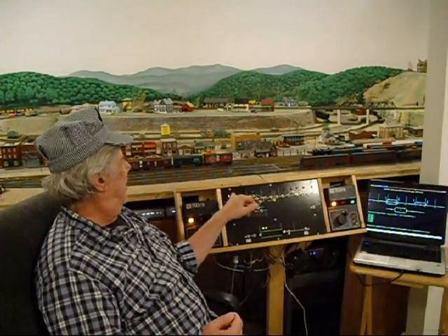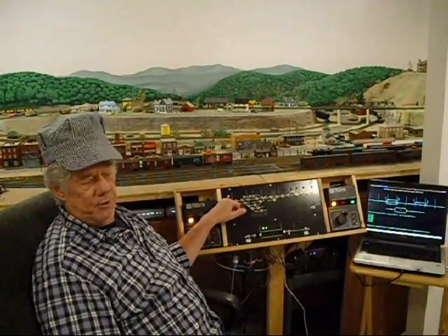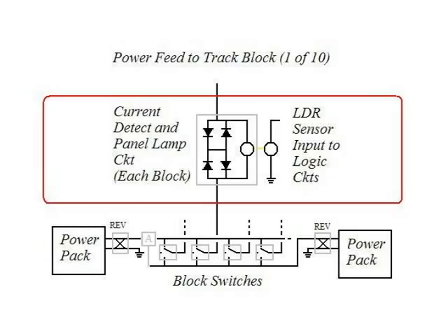And what I do is I bridge this lamp, which, by the way, is nothing more than a Christmas tree lamp, and it's rated at 3 volts across the bridge, so that if a train is drawing current through this thing, it will also create a voltage drop across the bridge and light up the bulb in either direction.